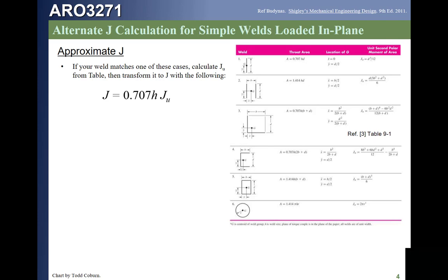So if you use this simplified approach for that kind of weld, you're going to need to make sure you orient your sign convention and communicate clearly in your work about where you're taking that centroid from. When you use that centroid to calculate, for example, the moment on that weld, you'll need to make sure you're calculating it to the correct point. In the same way, the X bar and Y bar are located in figures 4 and 5 for the C and the box weld in a similar manner, and you need to take the same kind of precaution.